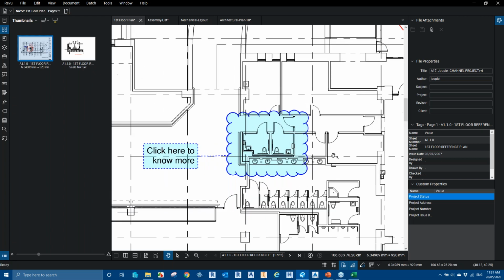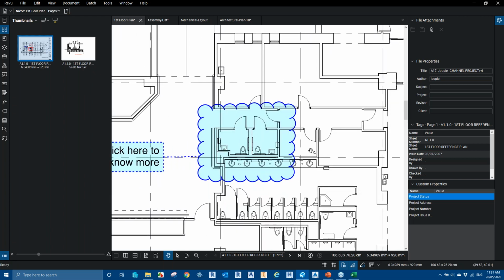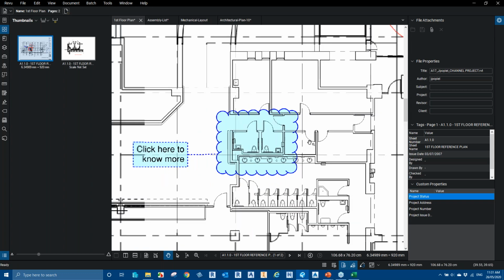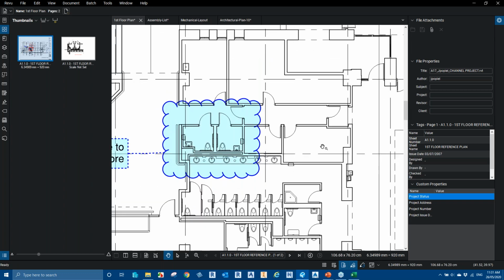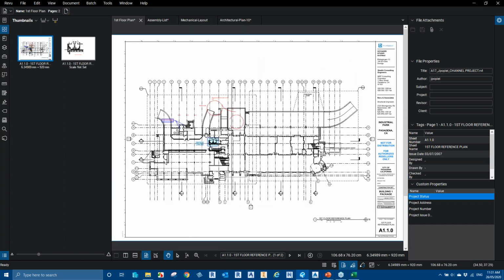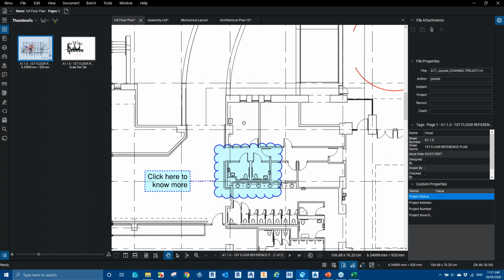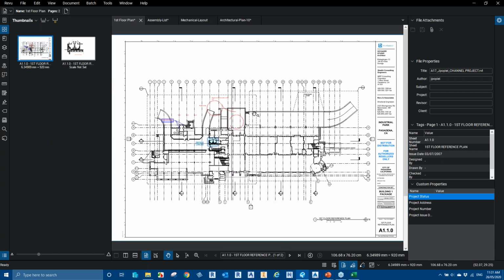By the way, an additional tip here, when you're working on CAD format size files, meaning A3 and above, scrolling back and forth is zoom in, zoom out. And you can also double click the wheel mouse button to do zoom extents. So double clicking the wheel mouse button is zoom extents, just like CAD programs such as AutoCAD and Revit.